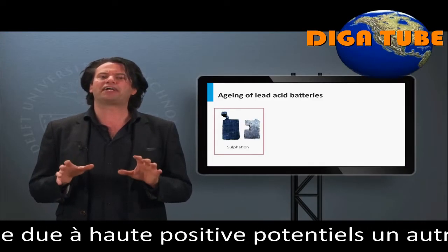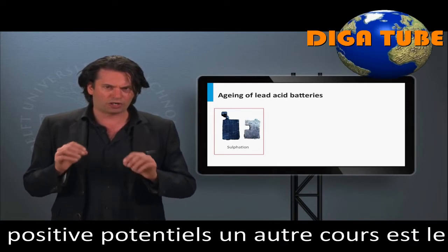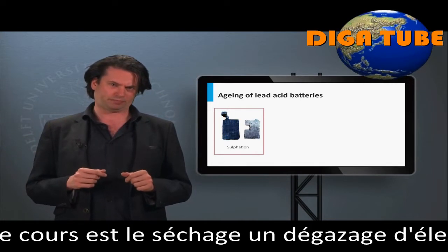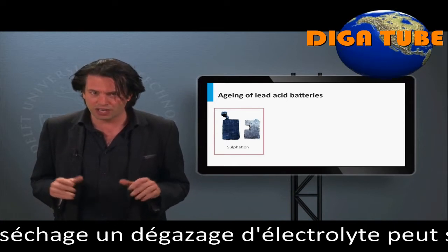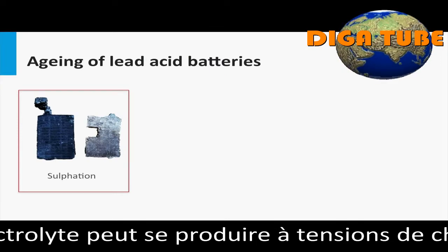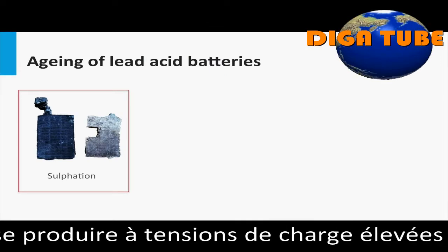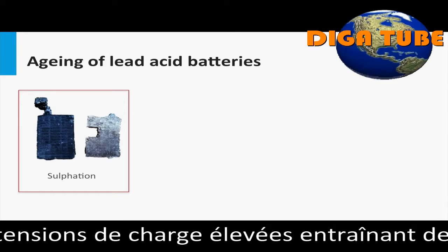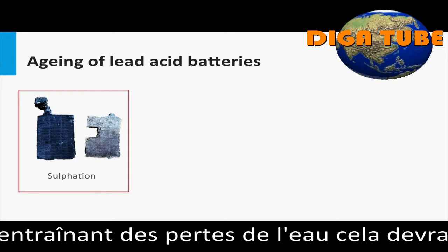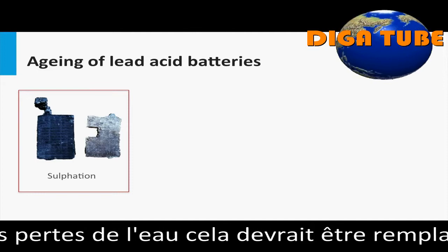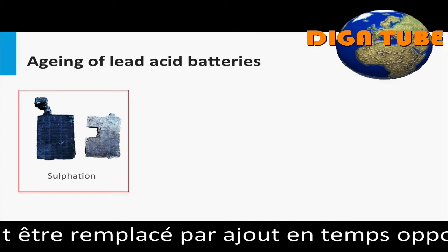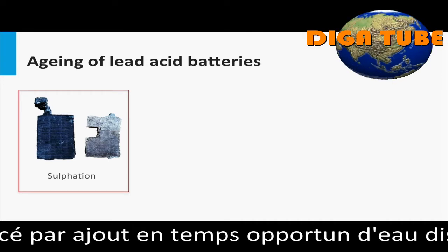When we say that the battery has a limited cycle life, or that it has permanently run out of use, what exactly happens to it? What exactly is this aging effect on the lead-acid battery? Let us briefly discuss this. Sulfation is one of the major causes of aging. Insufficient recharge after discharges cause sulfate crystals to grow, which cannot be completely transformed back into lead or lead oxide. Thus the battery slowly loses its active material mass and therefore its discharge capacity.